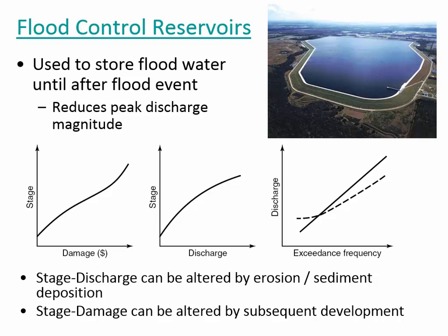People are starting to live in Barboursville and beyond Barboursville, even though there's still plenty of vacant homes and empty land inside the city limits. We just keep expanding and tearing down forests, and that's urbanization. And so the main disadvantage of flood control measures like this is that you can fix the exceedance frequency versus discharge curve, but then people continue to put expensive things in the flood zone. You really haven't solved any problem.